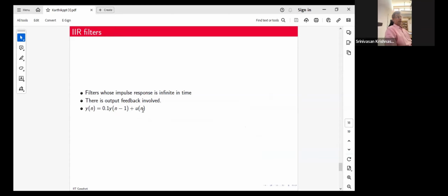Now, when you consider an FIR filter, you would take an IIR impulse response and truncate it, and then try to find an equation that gives you the same effect. You approximate the IIR impulse response by an FIR impulse response, and that's typically how the whole design process would go. You may not always want to implement IIR filters, so when you want to implement them as FIR filters, you would look at truncating the impulse response.